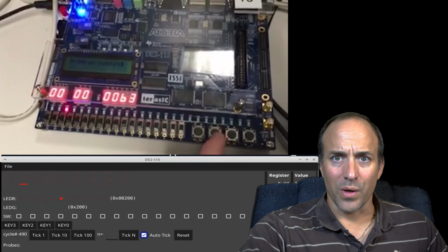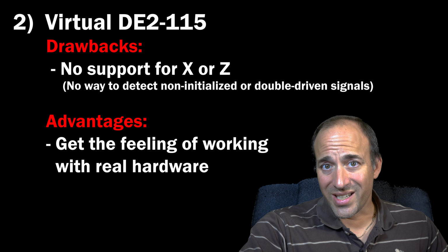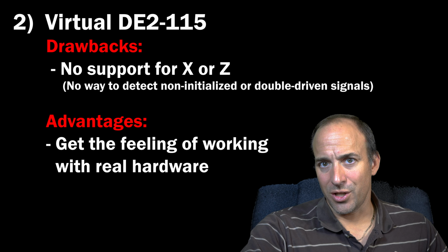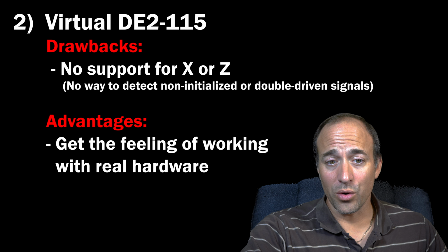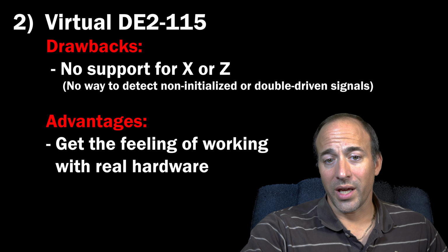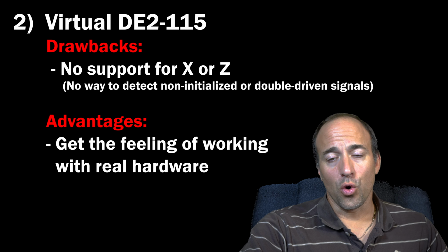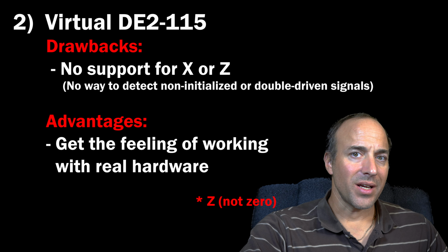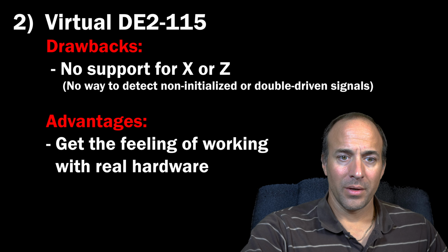The main drawback of Verilator is that it does not support the data types that are required by the SystemVerilog standard. Specifically, it doesn't understand concepts such as unknown, undefined, don't care, contention, or high impedance values, which, as I described before, are encoded as the X and the Z states of the logic type that we're using in the course.